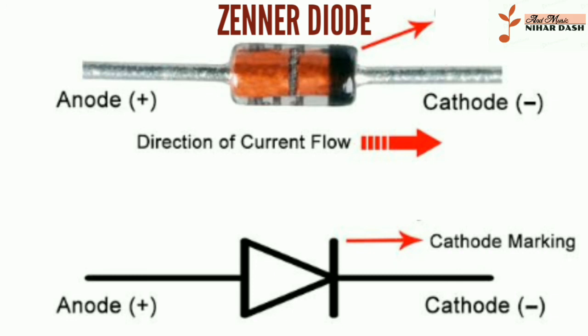The Zener diode is employed in reverse biasing. The reverse biasing means the N-type material of the diode is connected to the positive terminal of the supply, and the P-type material is connected to the negative terminal of the supply. The depletion region of the diode is very thin, because it is made of heavily doped semiconductor material. Zener diode connection. Working of Zener diode.